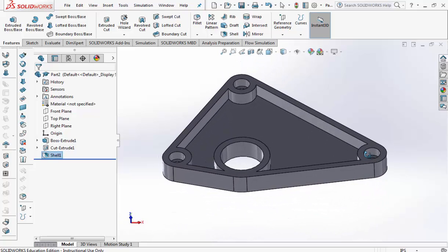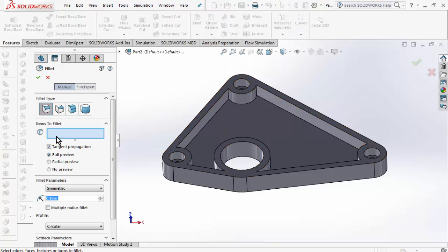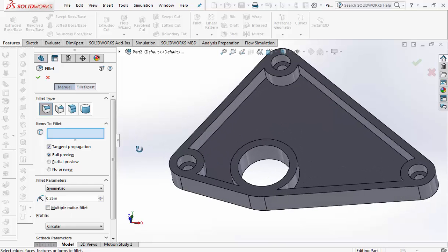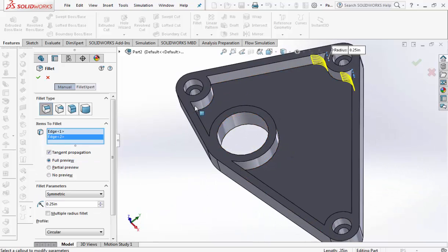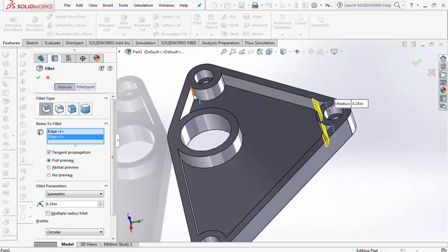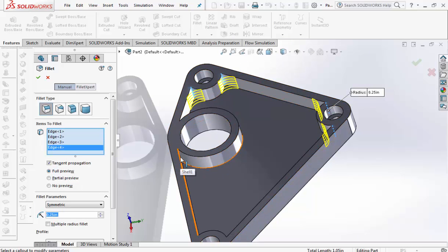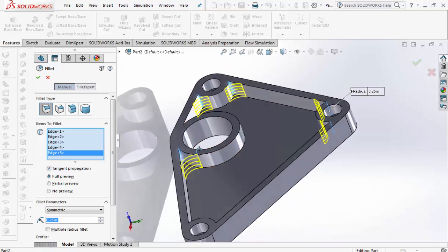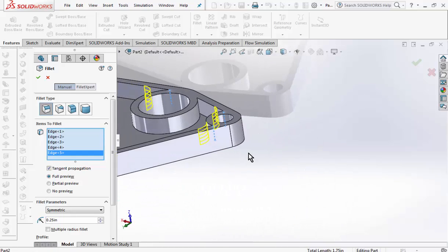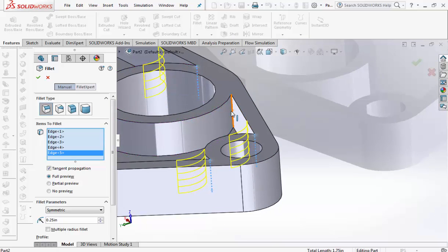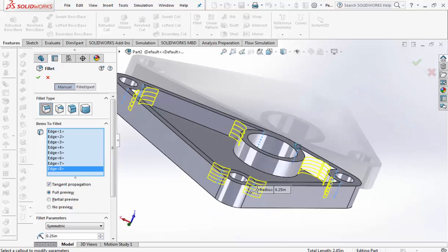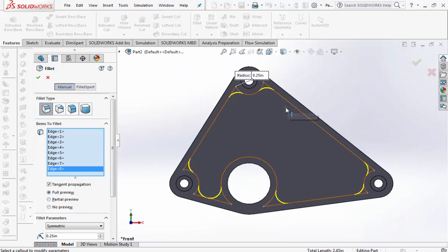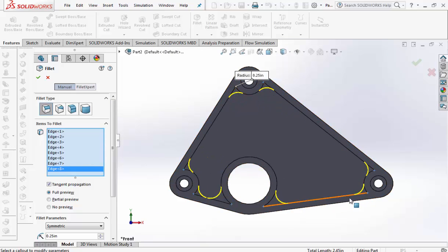Okay, so now we have to add 2 different fillets. So fillet, the radius, if we look at the handout, is 0.25. TYP stands for typical. Now we got to do this in 2 groups. I'm going to do the corners, the vertical corners first, so 2 there. Spin it around, get these 2. While we're at it, I'm going to try to get this one. Spin it around the other way. Get that one and this side. So there should be 2, 4, 6, 8. Right, so 1, 2, 3, 4, 5, 6, 7, 8. Hit the check mark.